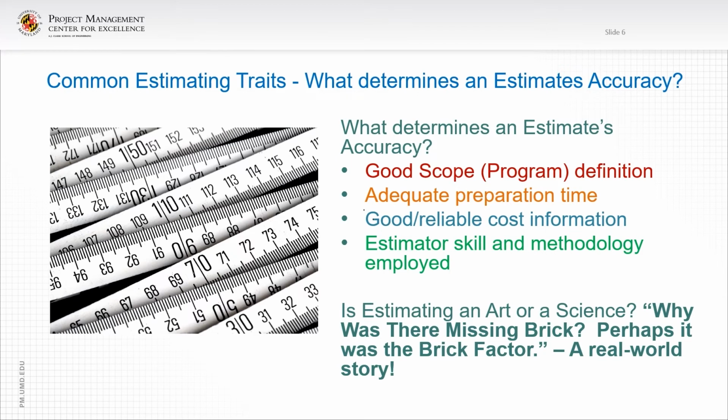If the brick factor on this particular job is actually 4 face brick per square foot, as defined, of a building surface area, and the total building surface area is 250,000 square feet, then the estimated number of brick needed is 1,000,000 brick. However, if you miscalculate, and if you calculate the brick factor in error at 3.9 brick per square foot, then the estimated brick needed amount would be 975,000 brick. This is what was used as the estimate on a real project.